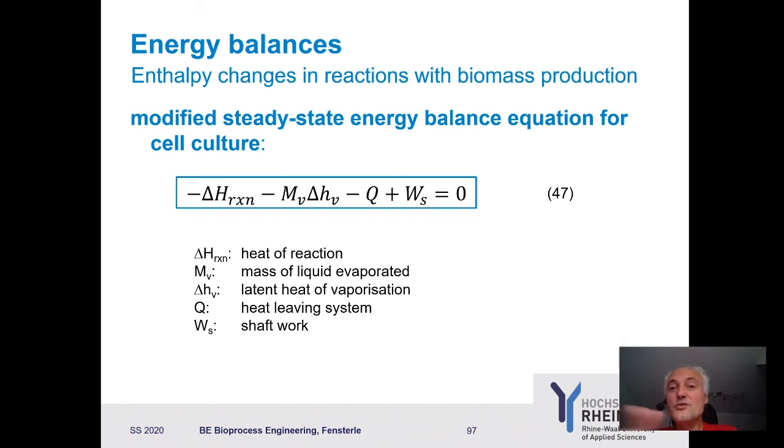So with this equation it was possible to calculate what we did before with this cooler. We had different temperatures, we had no change in the components, there was no reaction, but there we could calculate cooling requirements or the heat loss to the surrounding due to sensible heat changes. In this equation, there are no sensible heat changes anymore. We have dissected this equation.